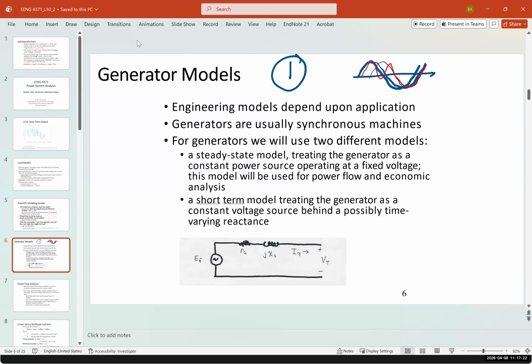If you measure the frequency of the grid right now, if I had an oscilloscope, I would show you. It's not exactly 60 hertz. It's like 59.8 to 60.2 if you want to measure it very accurately sometimes. So there is a little bit of cushion. And the voltage as well. It's not exactly 120. Sometimes it's going to be a little lower or higher. But that's acceptable, and that's the reason we have the system.